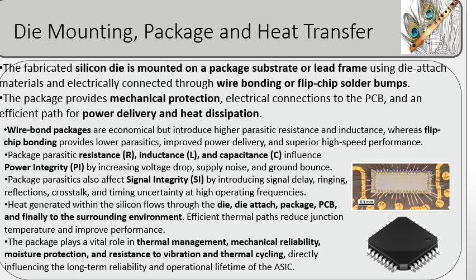Once the silicon die is fabricated, it is mounted inside a package that provides the mechanical, electrical, and thermal interface between the chip and the external system. The die I/O pads are wire bonded to the package leads. The package protects the die from mechanical and environmental damage.